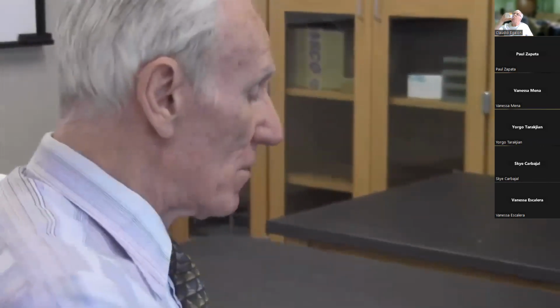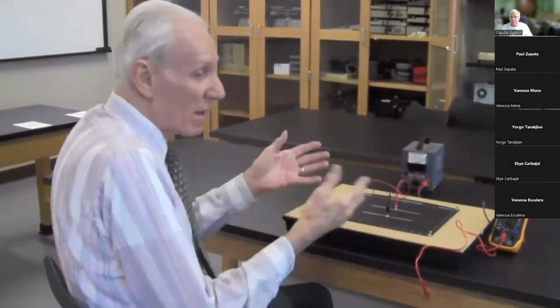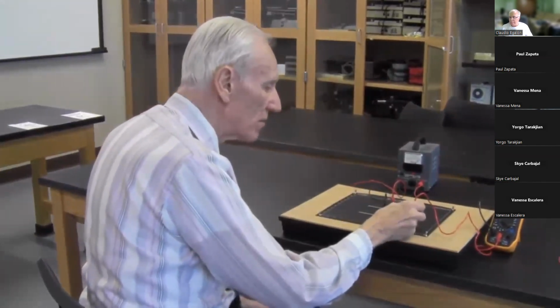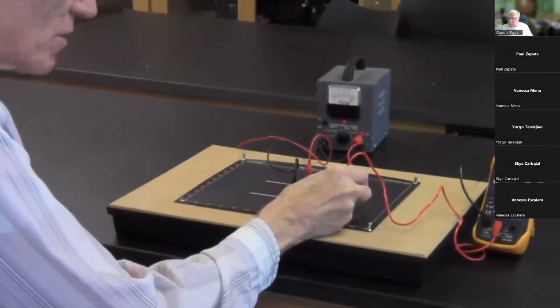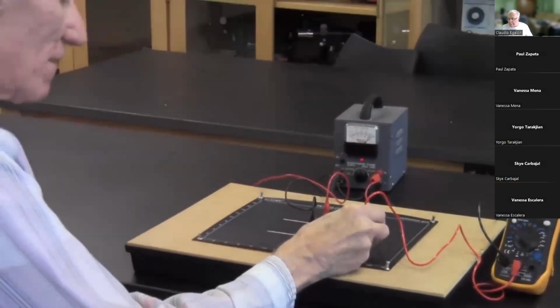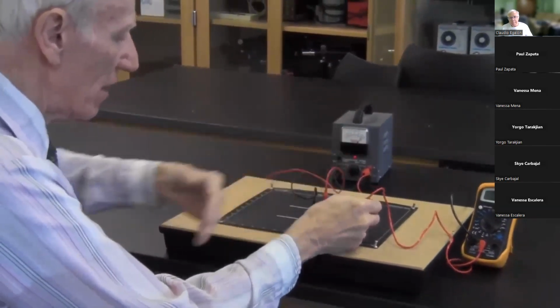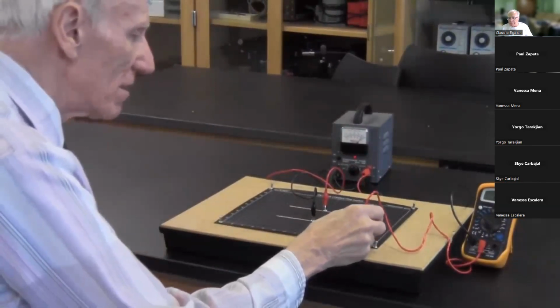No surprise, right? What you're going to get here in between these 2 lines are 5 parallel lines, essentially 1 centimeter apart. We'll talk about that a little bit later in terms of how you analyze these. But when it comes out here, let's look for the 2 volt line. I'll keep poking around until I find it. Getting warmer, almost there. Okay, there's a 2 volt point. And it's going away from this second line here, it's going off this way. So you want to look for that 2 volt line everywhere. There's got to be a 2 volt line out here someplace.